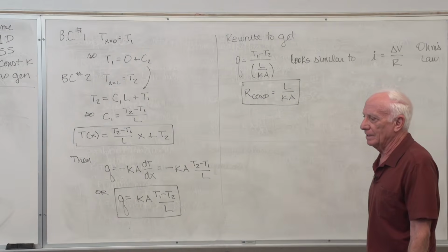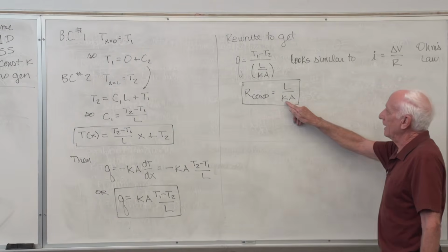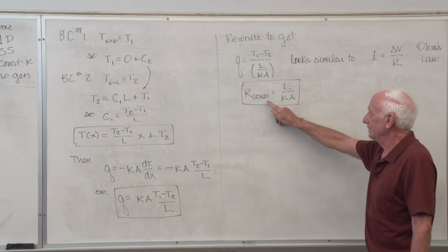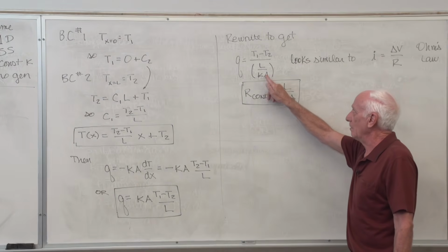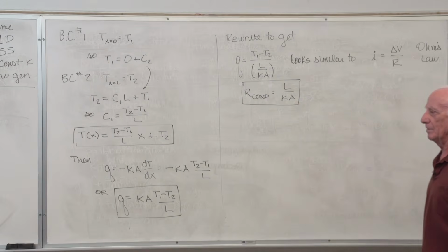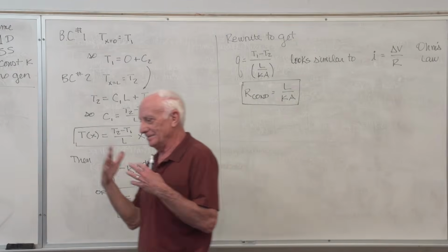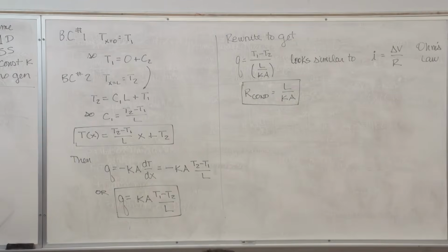k, copper and concrete. I know which one conducts heat better. k for copper, really big. The resistance is going to be really small. If this is really small, that's really big. Q through copper, bigger than Q through concrete. That makes common sense. So the resistance does relate to your thoughts on what should happen.